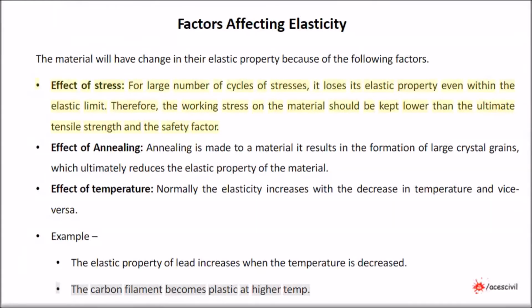Therefore, the working stress on the material should be kept lower than the ultimate tensile strength and the safety factor. Effect of annealing: when annealing is applied to a material, it results in the formation of large crystal grains, which ultimately reduces the elastic property of the material.